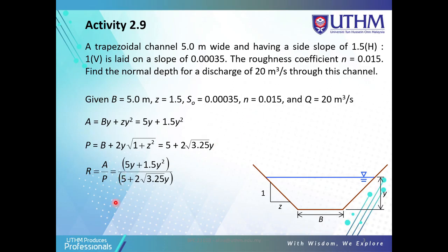Okay, so R is equal to A over P, so you just put it here. Okay, so we get the equation here. We use this one because we want to find the normal depth here, just in terms of y, because we don't know y, the normal depth.